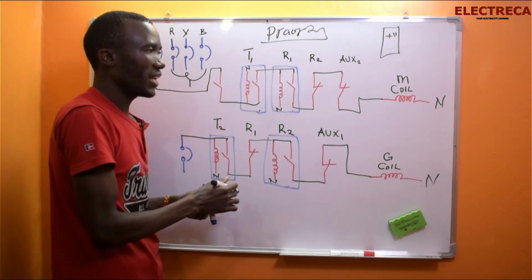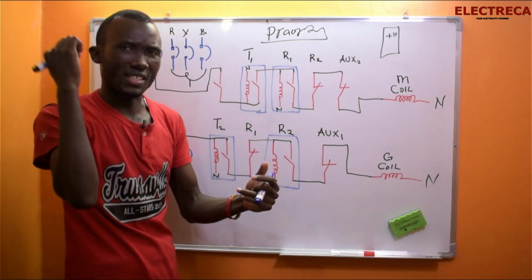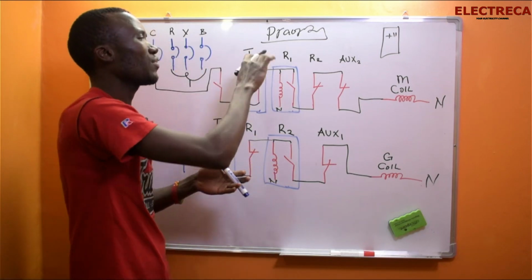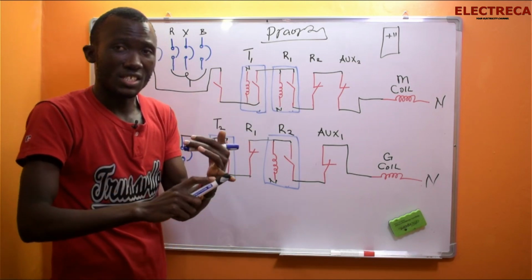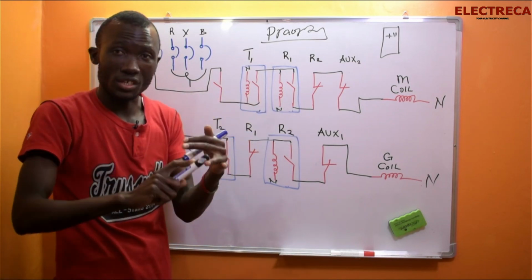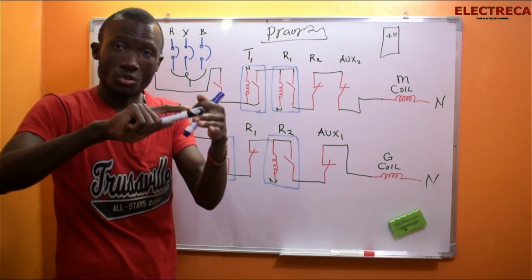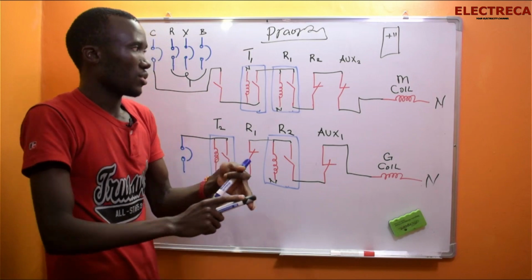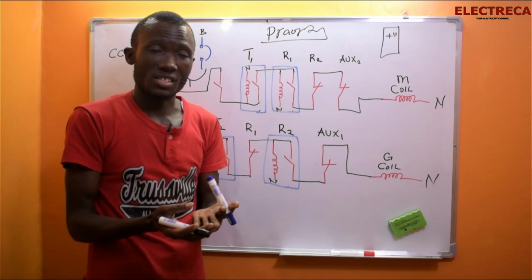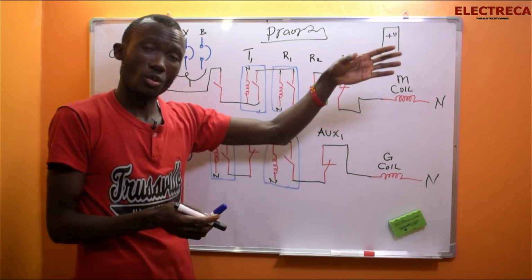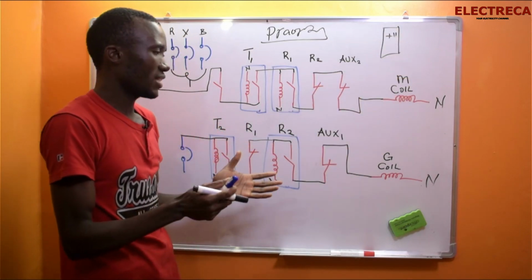Secondly, the relay is also helping us to send a signal to the generator. And you're going to have so many things here. You will have indicator lights. You have signal to the generator. You want to make electrical interlocks, you understand? So you cannot do all those without the relay because they have many contacts. You cannot do that on all of them on the contactor. So I hope that answers your question.